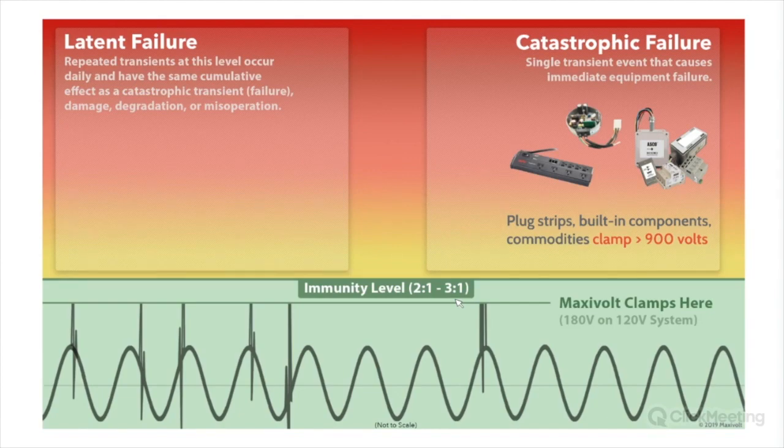If it's the current that's the problem, you have overcurrent protection built into your system because you have circuit breakers. Right. And so again, that's kind of the thing we're trying to illustrate and point out: you need to understand the voltage limitations, the voltage requirements. Our industry doesn't really focus on voltage protection as well as it should. When we look at things from an equipment perspective, from a reliability perspective, the surge current is more for lightning protection,